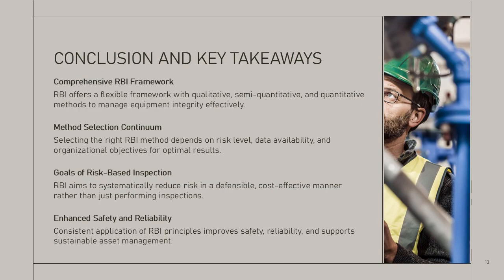In conclusion, risk-based inspection as defined by API RP 580 and 581 provides a comprehensive and flexible framework for managing equipment integrity. The availability of qualitative, semi-quantitative, and quantitative assessment methods allows organizations to tailor their approach based on risk, data, and objectives. Understanding the continuum of RBI methods and the factors influencing method selection is essential for effective implementation. Each method has its role, from initial screening to detailed risk optimization.